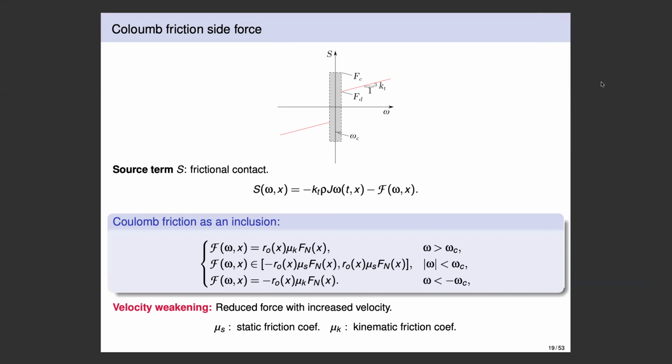And how do you manage when you are close to the absolute value effect, when you change the speed, the sign of the friction? It's not very easy to linearize that part. No. So we linearize it around an equilibrium that is in the linear part, basically. But that's only to compute the gains. Once we have the gains, then we use them on the nonlinear model, where there's no need for linearization anymore. Okay. Zach, it's your turn.